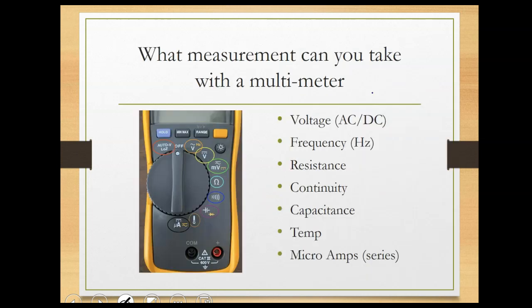Again, this is another multimeter by Fluke. I think it's a 116F, and look at the function it has here: voltage, AC and DC. So the straight line is DC, which you see in here, right? And the squiggly line, that's AC. And if you look at the Hz here, that's the frequency.